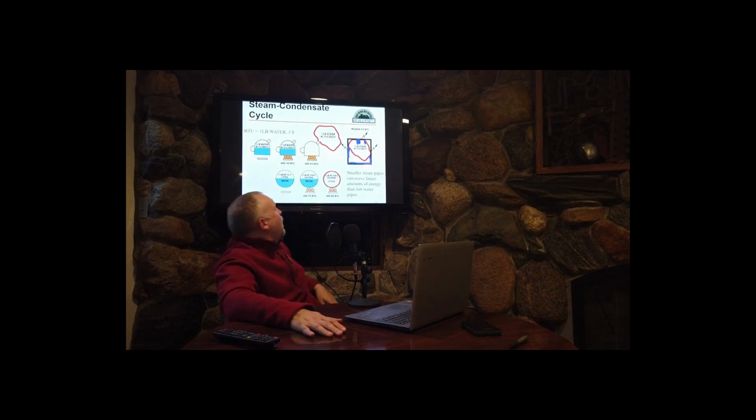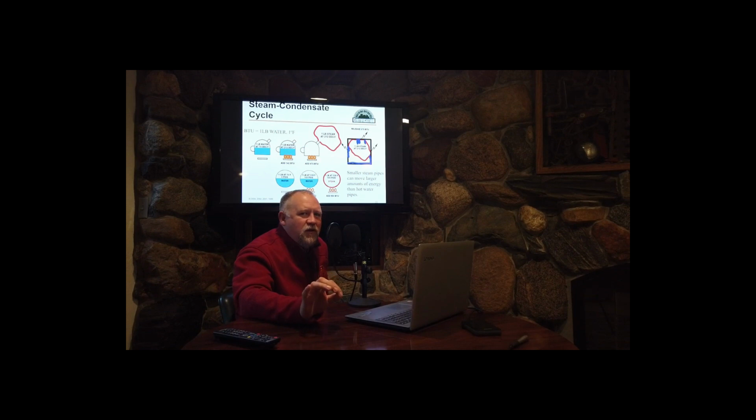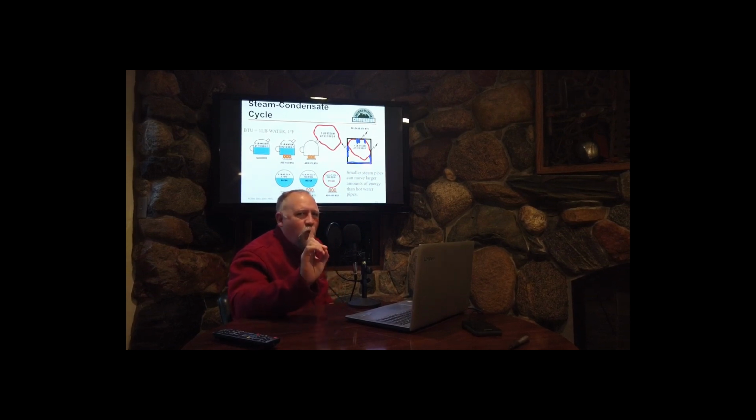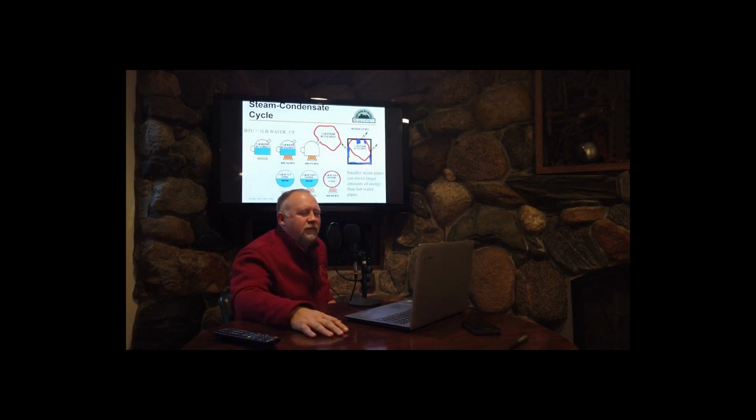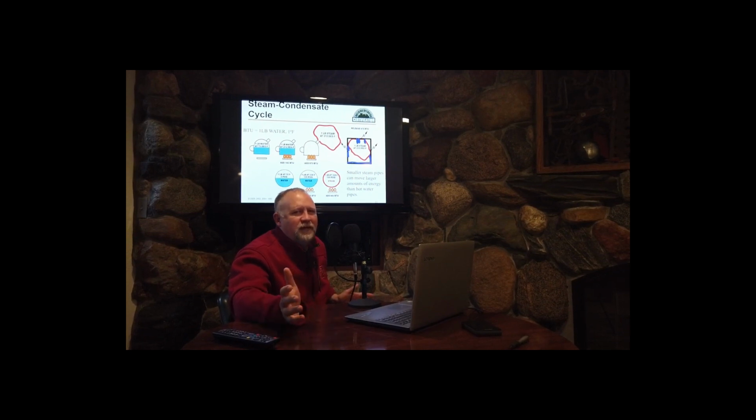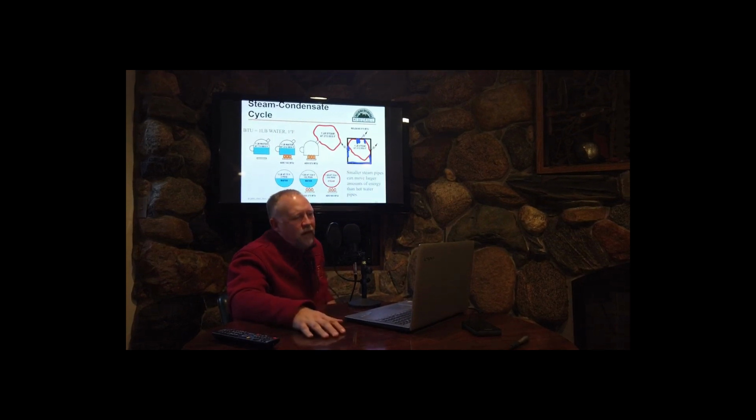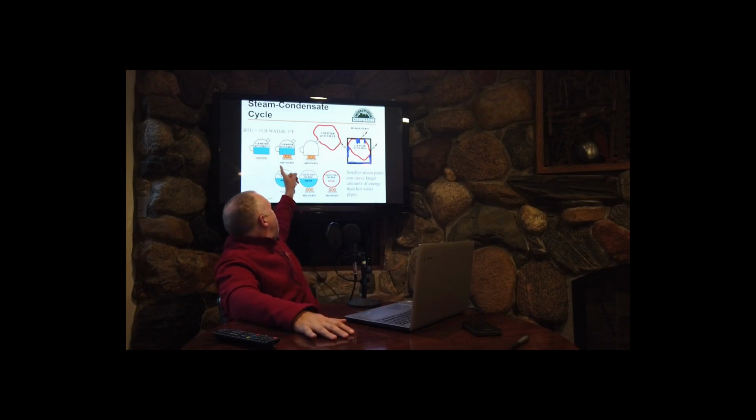degrees. Remember, the amount of energy that it takes to raise 1 pound of water 1 degree Fahrenheit is 1 British thermal unit. I know. SI units are easier to use and understand. Sorry, we're still using English units here. Even if the British don't use their own units, we're using them because that's the industry that you're going into, or at least learning about. So we add 142 BTUs to get it up to 212 degrees.